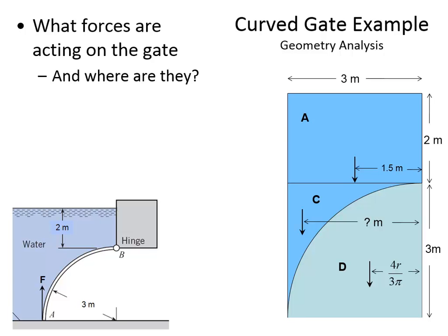It's 3.5 meters times the unit weight of water, and multiply by that area of the projection, which is 12 square meters. That is 4 meters by 3 meters. We're talking about the area of the vertical projection. And that gives us that the magnitude of the force is 412,020 newtons.